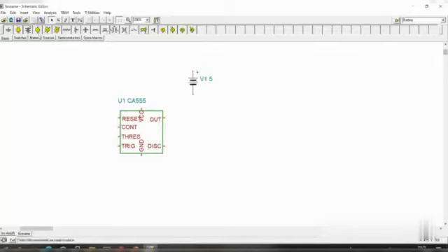That is the initial thing. And the ground, again I told you, you have to take it from here, drag and drop here, just for you to understand. I have done it for the ECL331 IC only. So as you need to do, this is the ground connection, and this one should be grounded.